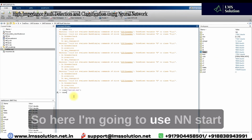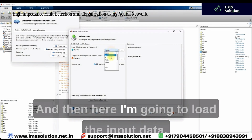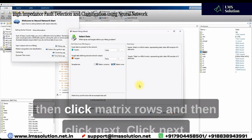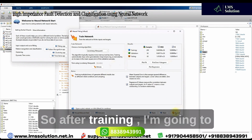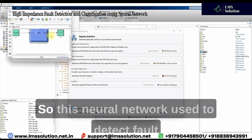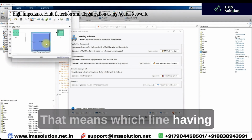Here I'm going to use nnstart, and then click the fitting app and click next, and then here I'm going to load the input data. Here I'm going to load the target data, and then click matrix rows, and then click next, and then here I'm going to train the neural network. After training, I'm going to simulate the Simulink diagram for the neural network. This neural network is used to detect the fault as well as classify the fault, that means which line has the high impedance fault.